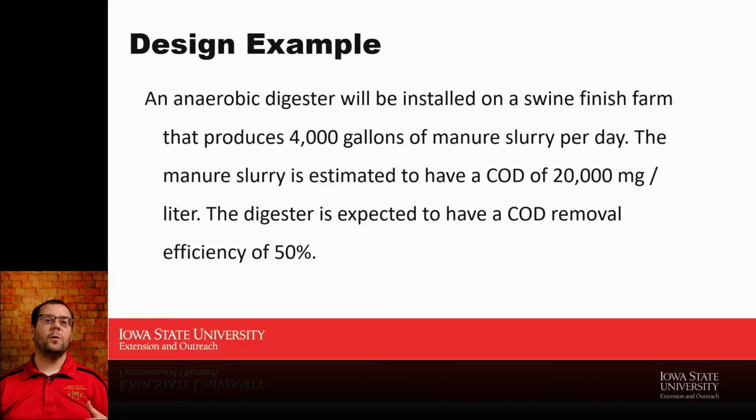My work there was all talking about per unit of volatile solids. That's how we've normally done it. There are some instances where people work off chemical oxygen demand because chemical oxygen demand is really easy to test. In my lab, I can measure chemical oxygen demand in roughly 4 hours. Running a biochemical methane potential will take me something like 35 days. So if you want to screen materials to say, is this even feasible to make a digestion project, we'll often start with chemical oxygen demand because it goes quick and easy and at least tells us if we're in the realm of possibility.